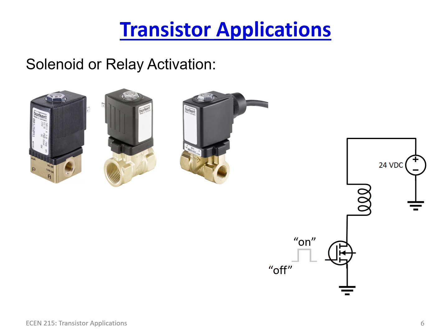So basically, if I have current flowing through the coil, I would end up with airflow. In this case, 80 psi shop air would go through, and it was a ported valve, meaning that if the solenoid is off, it would stop here, so I'd have 80 psi here. And then over here, it was vented out, so we'd end up with 0 psi here.